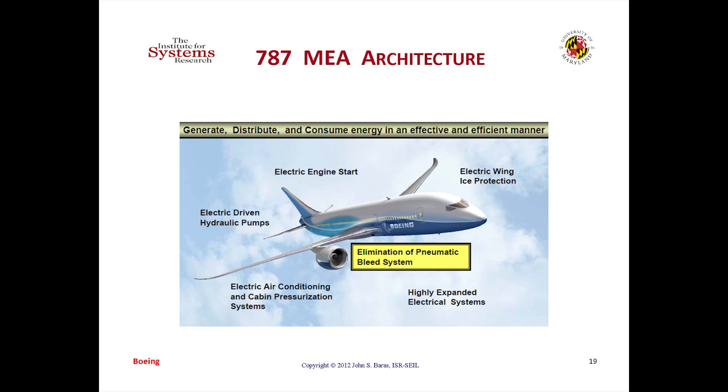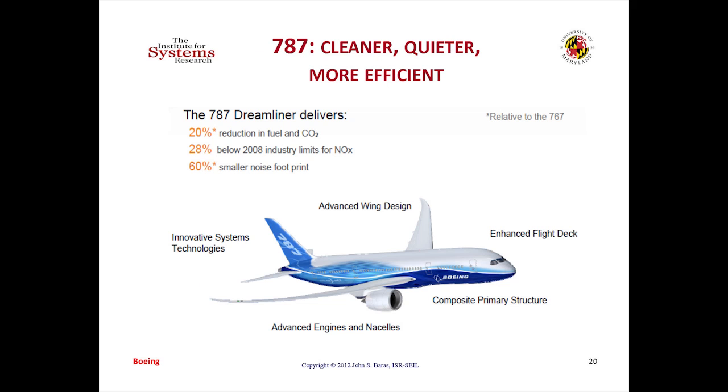There are many interesting systems engineering problems here that Boeing did, beautiful work, to relate the properties of the composite wing. That's when they proposed it, everybody thought they were crazy to do a composite wing aircraft, with the abilities of the controller to navigate the aircraft in smaller space than with conventional wings. Okay? So this links very difficult physical properties, where the material is a design variable, with something like the guidance control of the aircraft. Also, there are no pneumatic controllers. Everything is electrical, okay, in this aircraft. That makes the vehicle management system a monster, right?